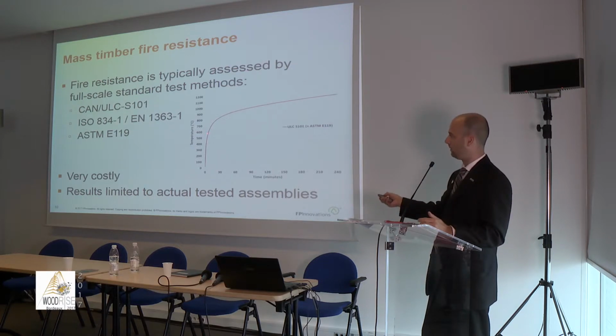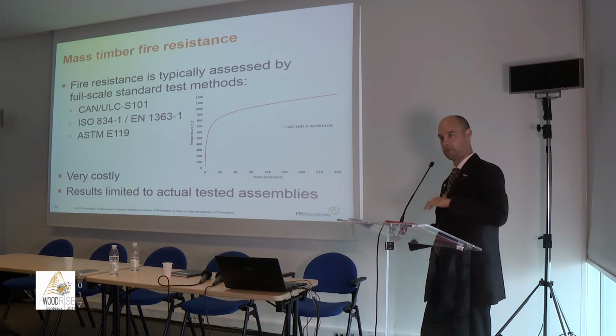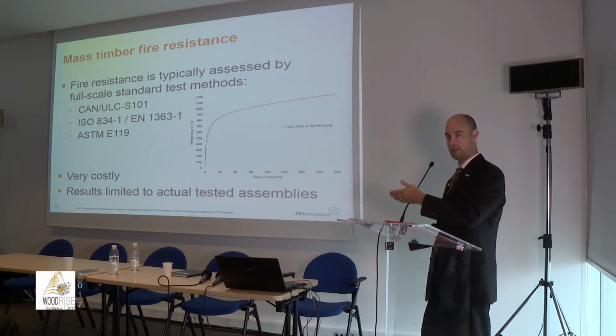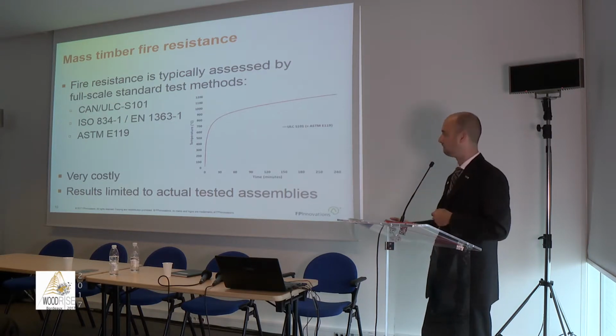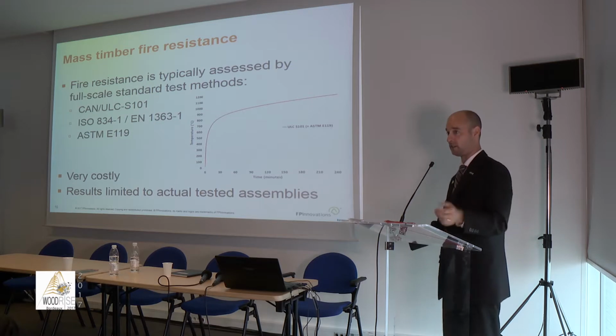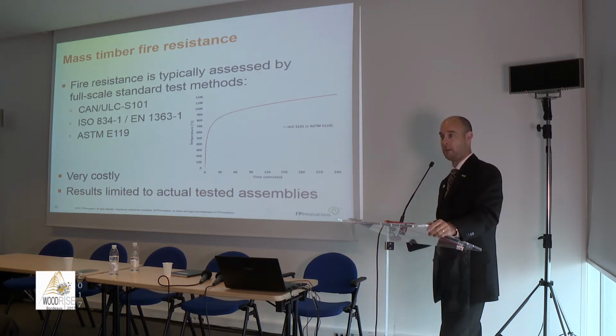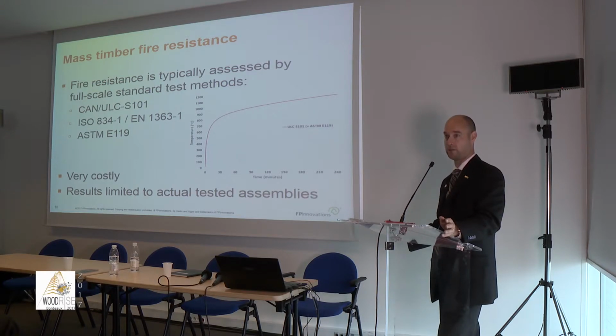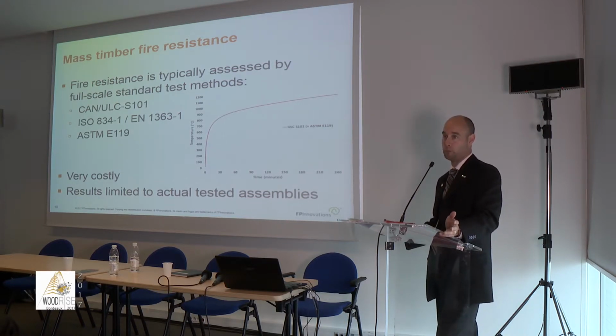You have a rapidly increasing fire in the early stage, and then it keeps on going and going, as opposed to, for example, the Japanese fireproof test that is up to 1 hour, and then you go to the cooling phase. It is a test that is really costly. It's essentially a one-shot deal. So once the fire test has started, you cannot just stop to adjust something. And typically the result is applicable only to what you just tested.